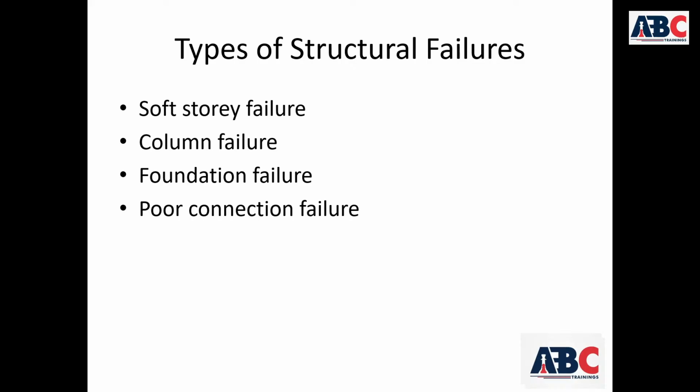Liquefaction occurs in sandy soil when ground shaking increases pore pressure. The soil loses strength and behaves like a liquid. This can cause tilting of buildings, sinking, and complete overturning.